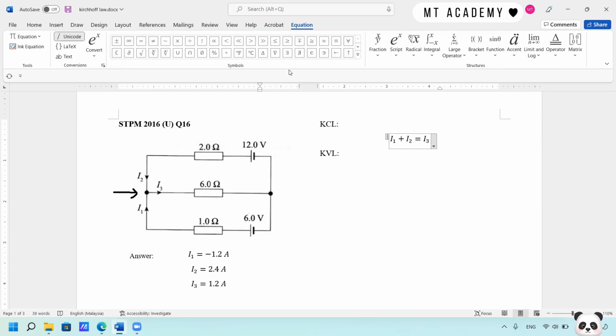And then we're going to use the Kirchhoff voltage law, either clockwise or anti-clockwise. To make the work simple, we should choose wisely. Usually I would observe the EMF source. In this case, I'm going to draw an anti-clockwise direction because it flows out from the positive terminal of the 12-volt battery. And also, I2 and I3 follow the direction of the loop.